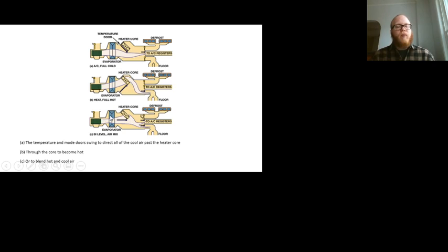Or maybe we've been driving for a little while and we don't need full heat anymore. The cabin's warmed up enough so that we can do a nice mixture of the two. Now the evaporator is pretty easy to control what the temperature is of it. It's either pretty close to 32 when the AC system is running and the compressor is being spun by the belt, or it's pretty much ambient temperature because that's what's getting blown across it, and no refrigerant is flowing through it at the time to keep it cooled down. So that's the state that these are in most of the time, honestly.